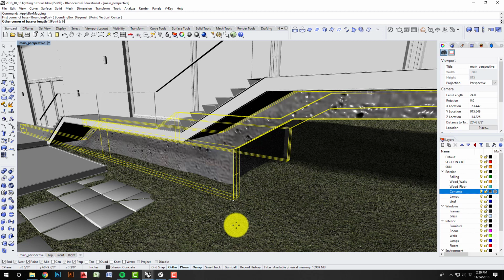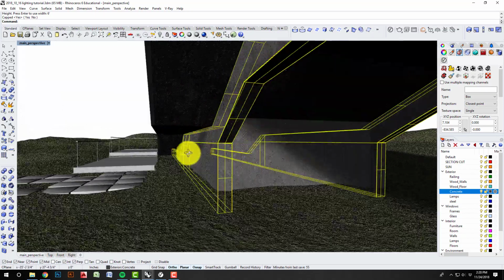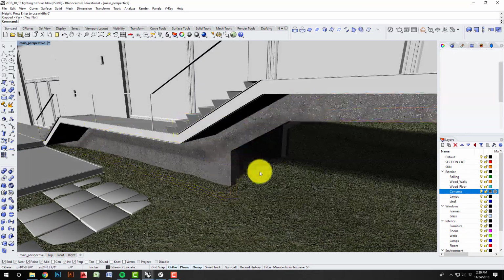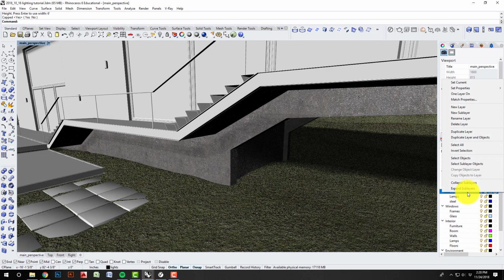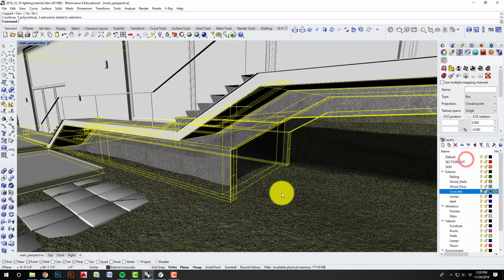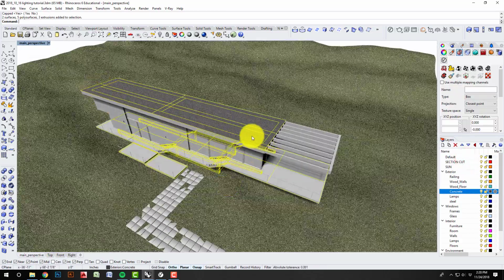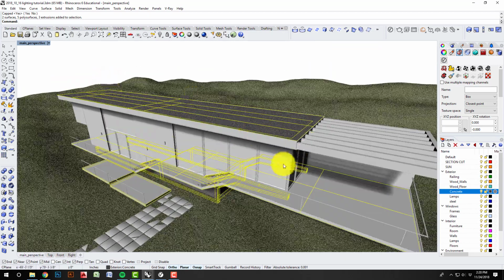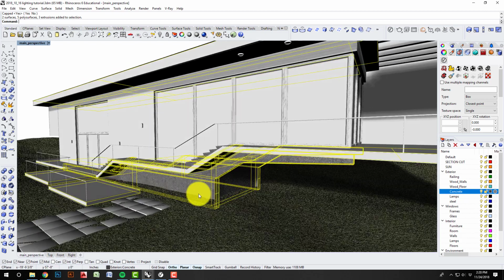So I'll do 6 feet by 6 feet by 6 feet, enter again, and now that scale looks right. And just to be sure that everything on that layer is on that, I'll go to that concrete layer and right click and go to select objects. So now I've selected everything, and you can see the ceiling, or the roof of this model, is also concrete.